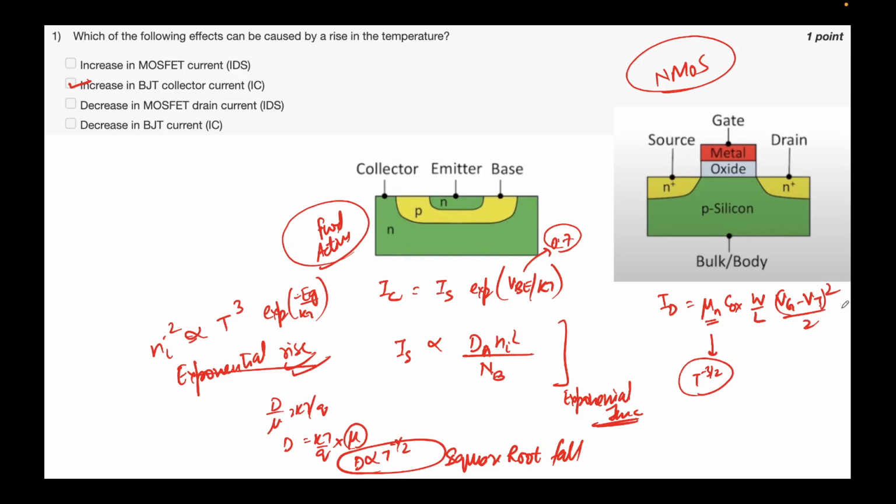Vt slightly decreases, but that is more or less a logarithmic decrease. When we come to the expression for Vt a few slides later, you will be able to see what I'm talking about. But for now, we'll see that Vt decreases logarithmically. This means Vg minus Vt will increase, but again logarithmically, and this is a 3/2 dependence. So this dependence will naturally win over the logarithmic.